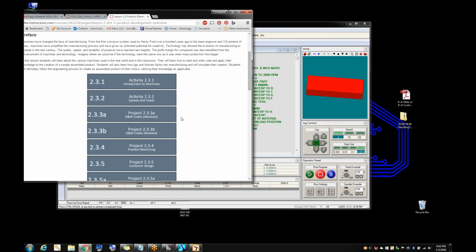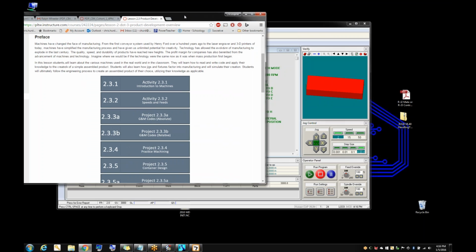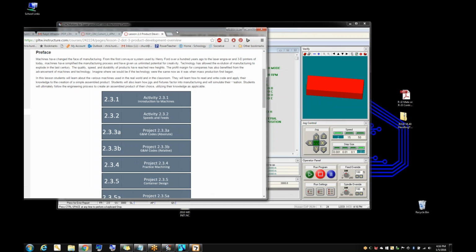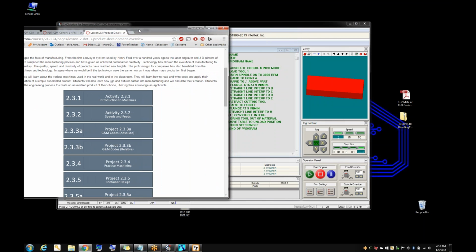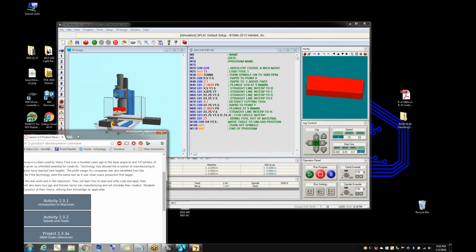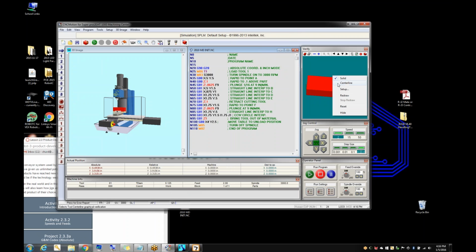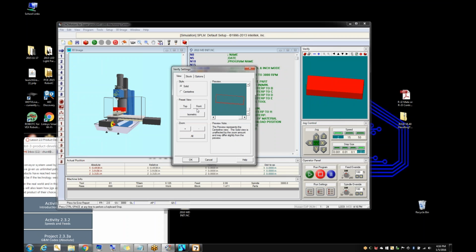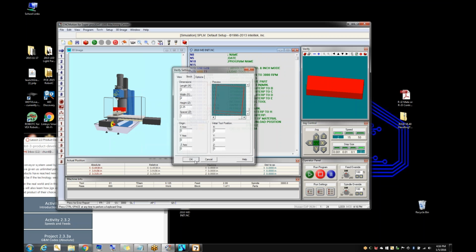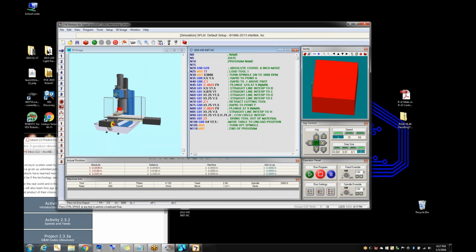Gail, Brian, Nathan, any of you have some? Have you gotten through this G&M code? I've done it myself and done my initials into the wax just to learn it from my end. That was before Christmas. The kids haven't got to it yet. How did that go for you? Once I got the piece locked down into the mill firmly, it went really well. The first time I didn't have it down firmly enough, and the block moved all over everywhere, and I had to stop that.